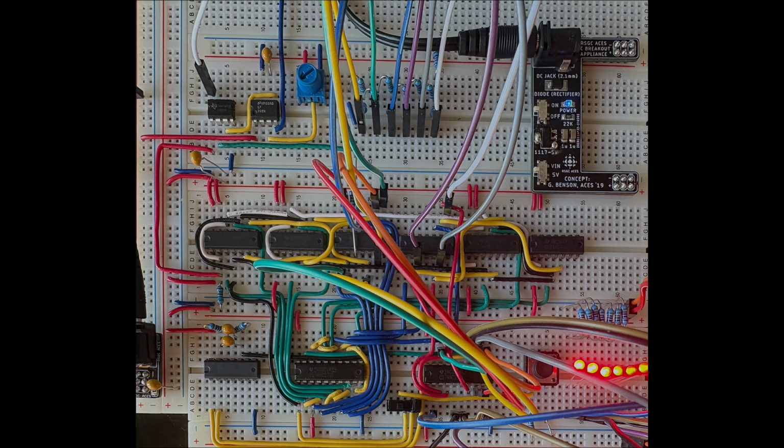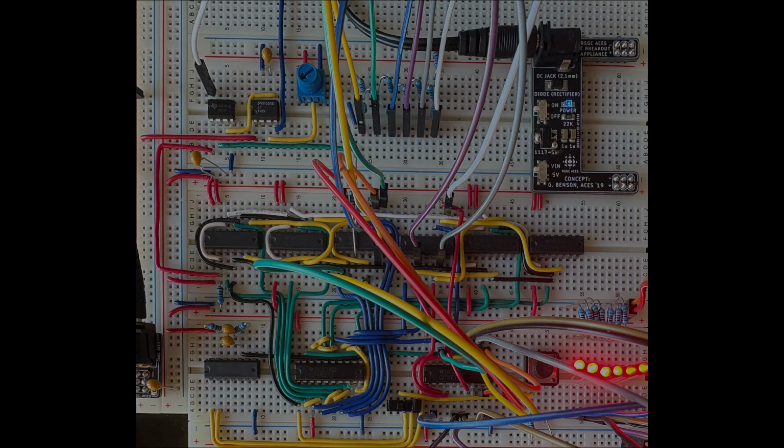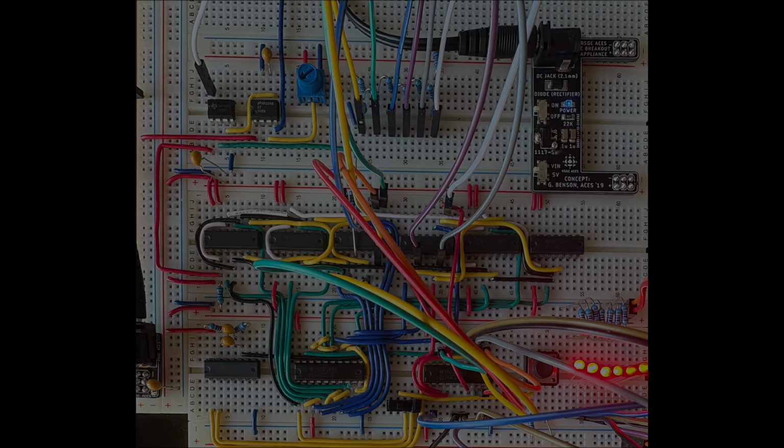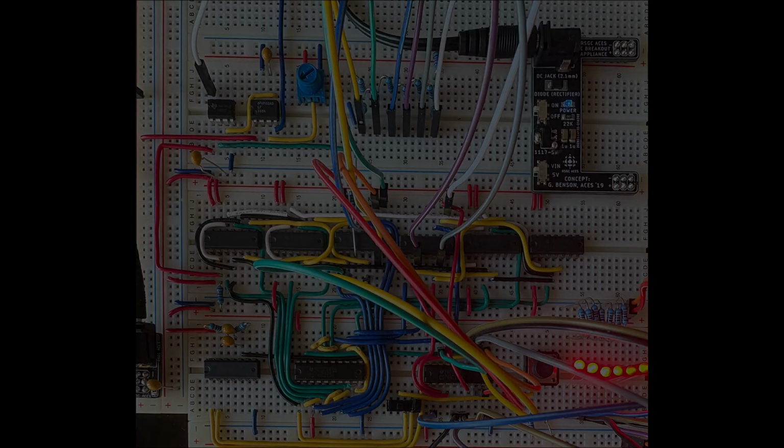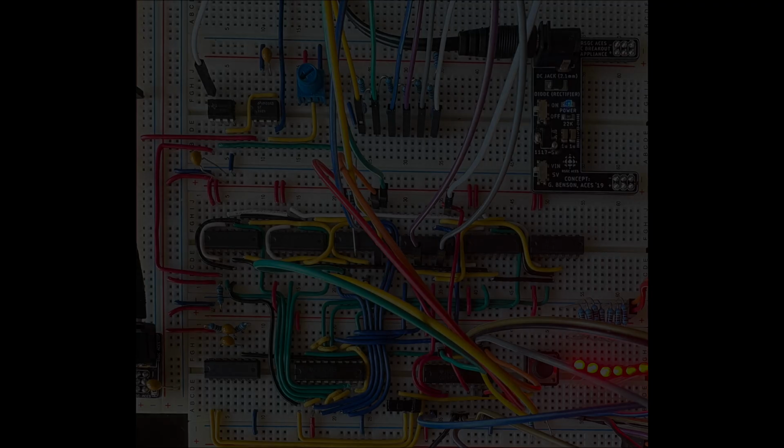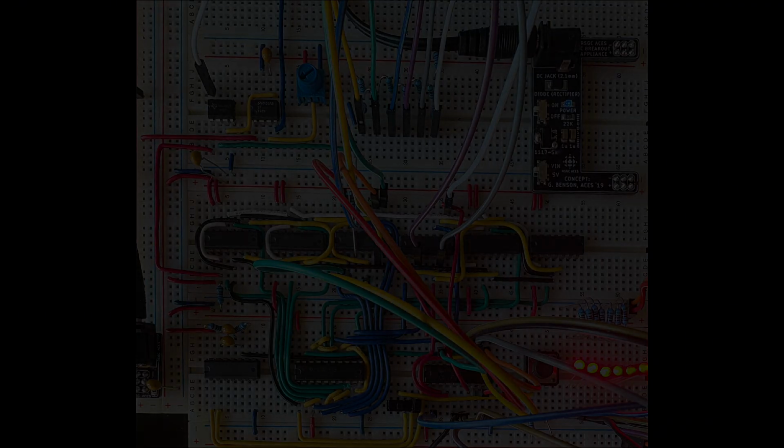In conclusion, this project demonstrates how an analog voltage can be converted into a digital value using the successive approximation algorithm, implemented entirely with discrete components. By constructing the clock, SAR logic, DAC, comparator, and sample and hold stages individually, the project provides a clear understanding of how many modern ADC systems operate internally. The completed circuit successfully converts a variable analog input into a 7-bit digital output displayed through LEDs, illustrating the relationship between analog signals and digital representation.